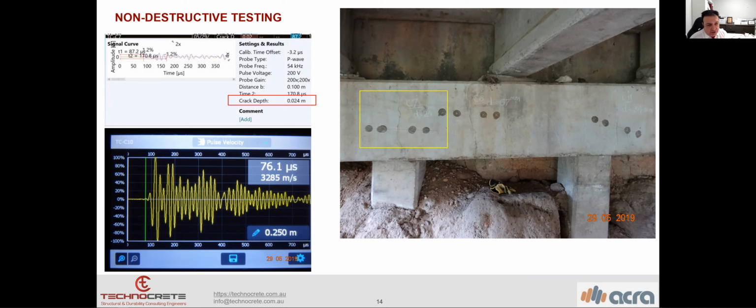We have to measure the moisture content. We have a special digital device which can measure the moisture content of the concrete. For example, some epoxy coatings need a specific magnitude of moisture content, let's say 3% or a maximum of 4%. Then we have to measure the moisture content first and then apply the other products and materials. Okay, thank you. No worries, interesting questions, thank you.